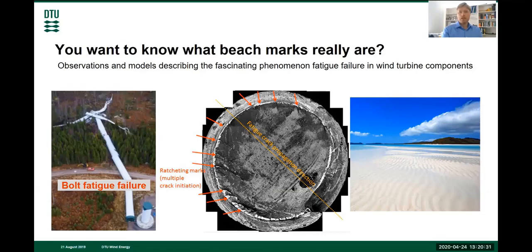And in fact, fatigue is the most prominent failure cause we find in wind turbines. And it can lead to catastrophic failures of the entire turbine, as you can see on that slide. But also fatigue in general has led in the past to severe incidents and also fatalities. It is a very insidious failure mode, as usually the fatigue crack initiates and propagates over a very long extended period of time, largely undetected. And when you detect it, it is usually too late.